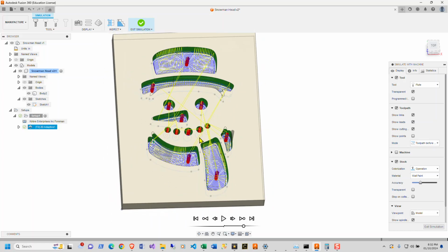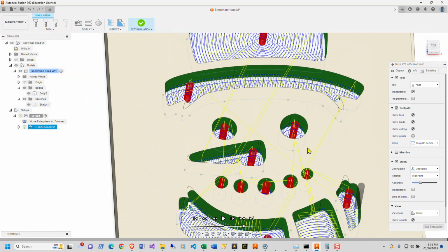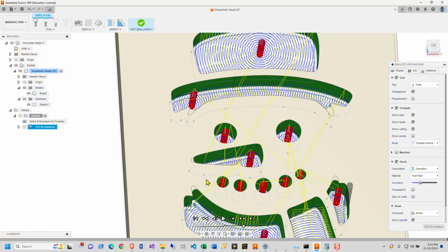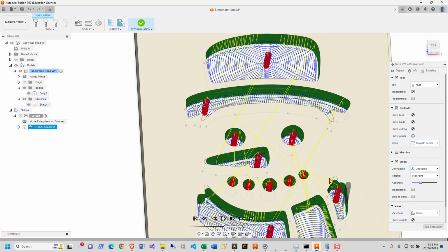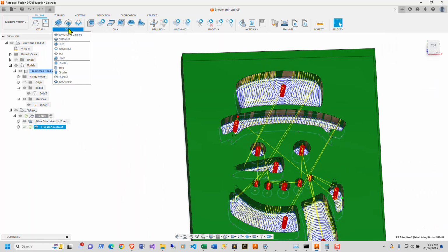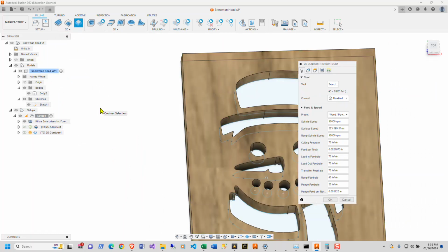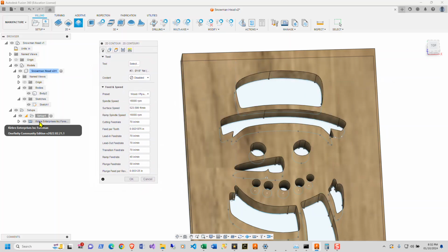These are really smooth cuts. So now there are a couple things that we missed. Like we didn't get this here, we didn't get this here. The tip of the nose, this guy here. So there is something else that we can do. Now we can come in and we can say, give me a 2D contour. All right. So the 2D contour is like a profile in CarveCo, but it's the contour. It's going to go around the outside or around the inside.